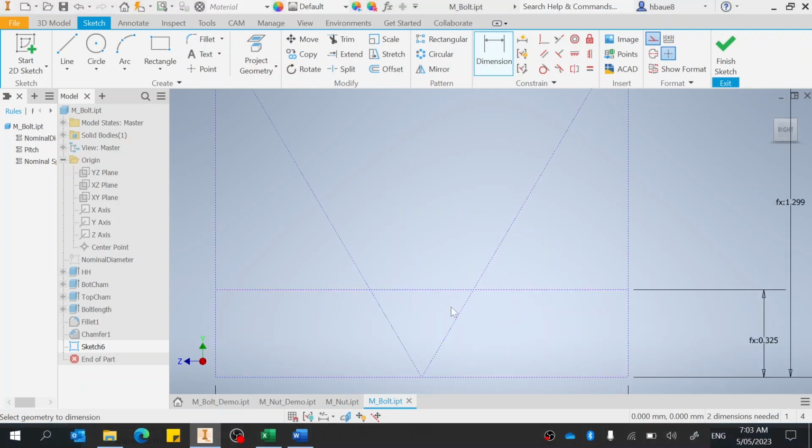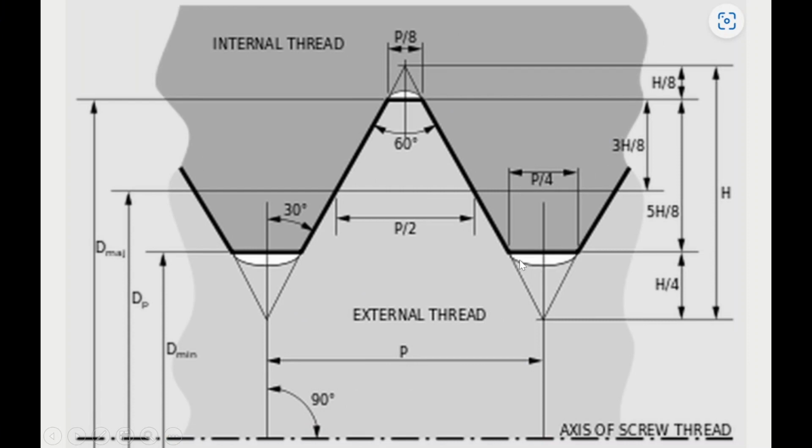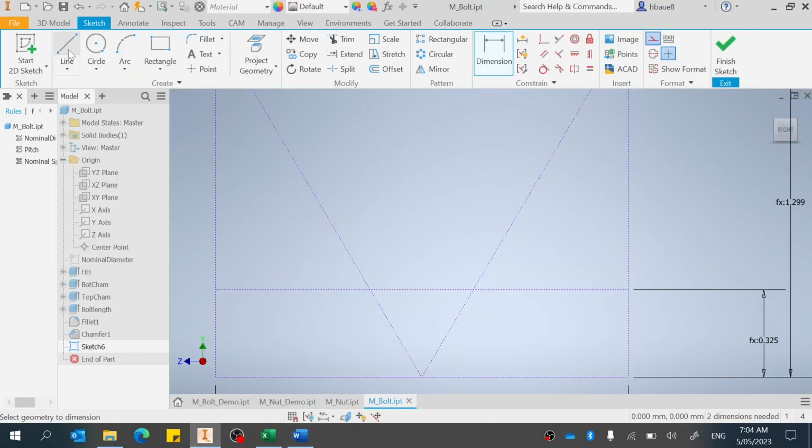And there's a little arc. That little arc can be chopped into the shaft, and for the internal thread there's a little arc at the top there. So to create that arc, we take a line perpendicular to the side of the triangle and take it into the middle, 60 degrees, wait for it to snap, and down to the other corner. Then, to make sure that locks how we want it, of course we're on the YZ plane. It looks vertical, but we're actually dealing horizontal here at the moment. We lock those 2 points.